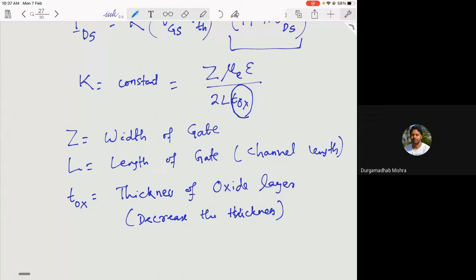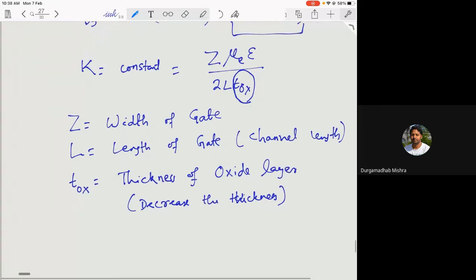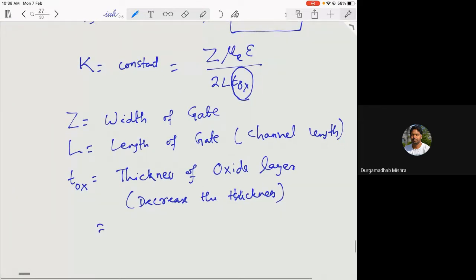Okay. But there is also a challenge in the fabrication, because typically let's say the thickness would be around 100 nanometer. Such a thin insulating layer, depositing it on top of your P-type semiconductor or N-type semiconductor is a challenge, and you have to make sure that it is really smooth and there is no roughness at the interface.